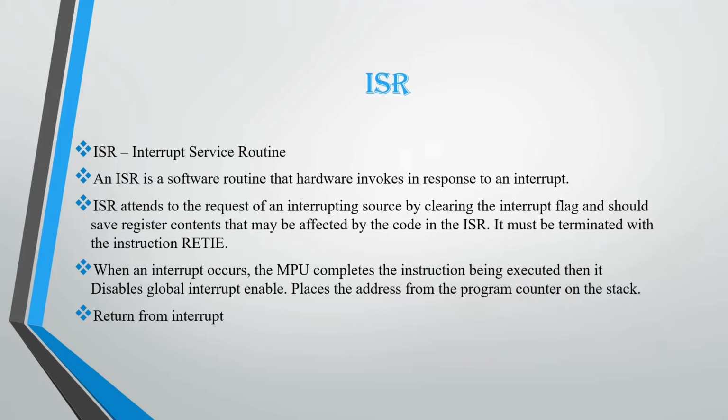ISR. ISR stands for Interrupt Service Routine. An ISR is a software routine that hardware invokes in response to an interrupt. That means a software routine that is called by hardware in response to an interrupt. The ISR attends to the request of an interrupting source by clearing the interrupt flag, and should save register contents that may be affected by the code in the ISR. It must be terminated with the instruction RETFIE.